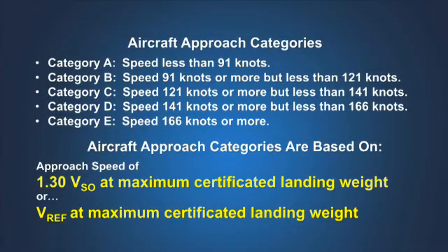With the adding of VREF to the regulations, the rule defining approach categories was also amended. For airplanes where VREF is defined by the certification rules, the approach category for that airplane is based on its VREF speed determined at its maximum certificated landing weight.